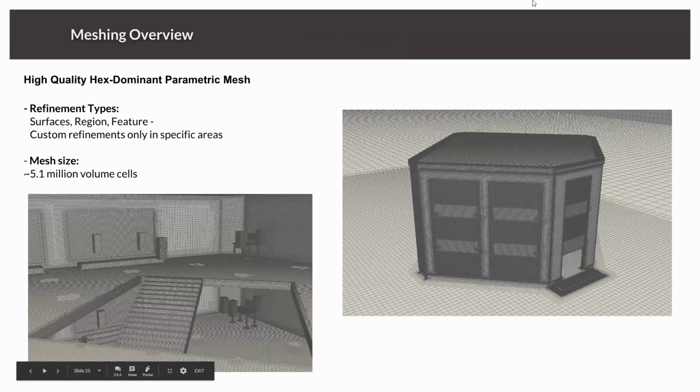The first thing we need to do is meshing, so we need to define our geometry. And here it's very important to use the right mesh size at the right place of the model. And don't forget that at the end of the day, the smaller these elements are, the more accurate the simulation is. Therefore near objects with sharp edges, we use smaller elements, and away from the building we use larger elements.